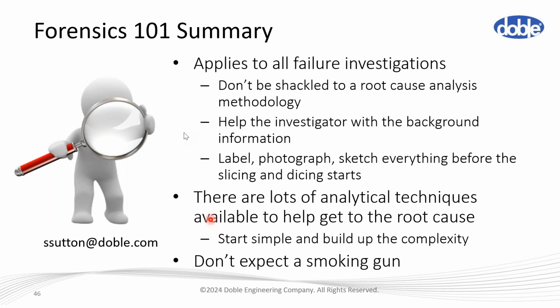High voltage, extra high voltage circuits tend to be longer. You have bigger joints, and so you can potentially do PD testing at the individual joint locations, either as a spot test if you have access to the cables, or people for EHV cables will often put permanent PD monitoring in these days.